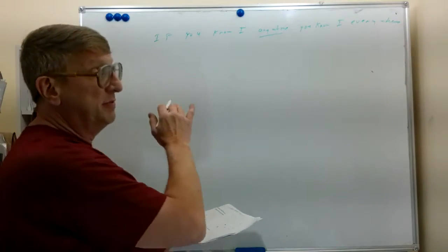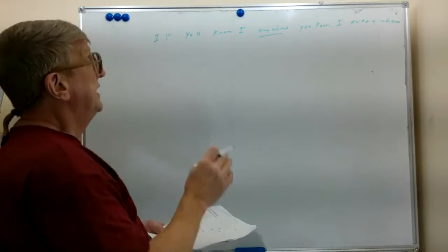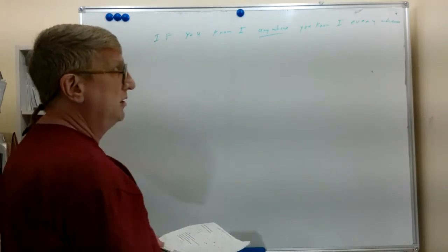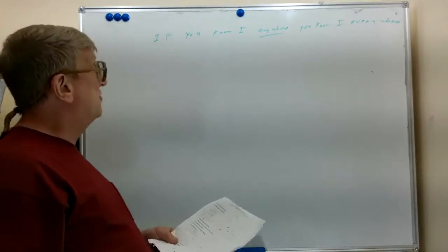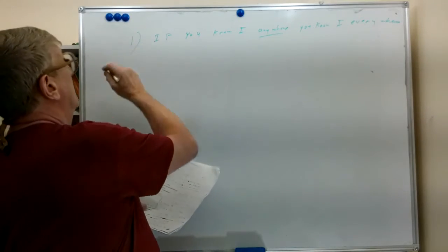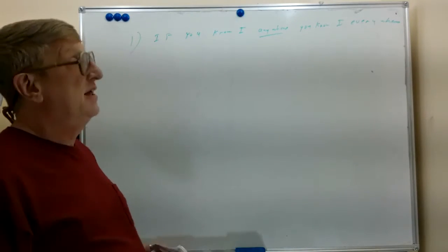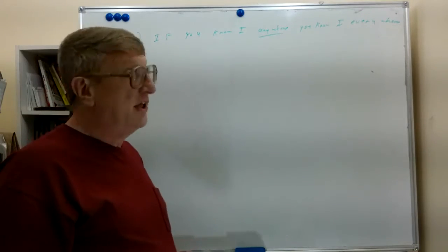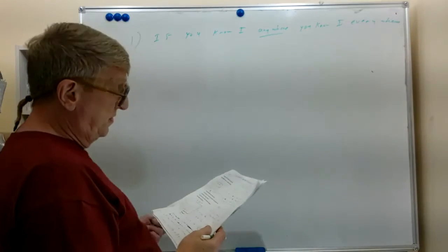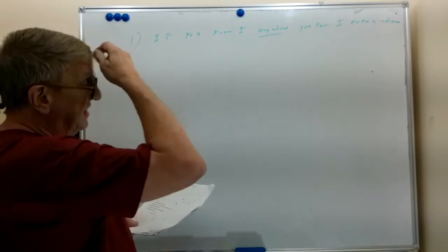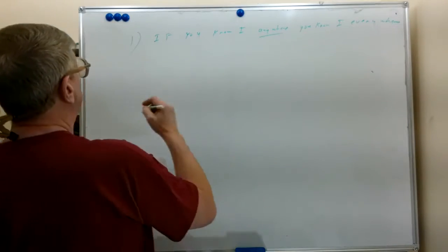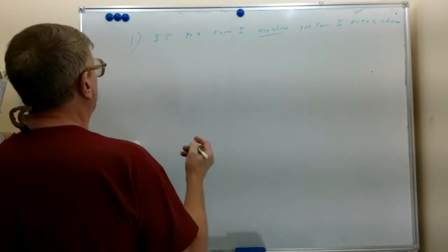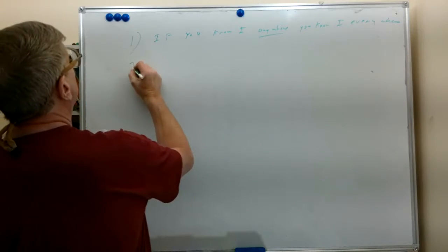So it's important to remember that the current is the same everywhere in a loop. If you're given the current, that's a nice thing. If not, maybe there's a resistor that they've given you the voltage value across or something, so you can find the current. You're going to need the current to solve a series circuit.